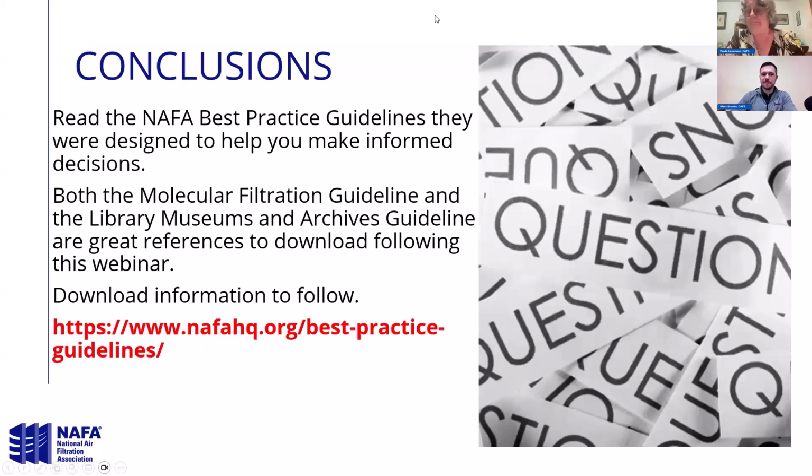Just be careful. I would not contact an engineering firm, no offense, but they have not come up on this yet. And that's to the detriment of those of us in the industry. We didn't teach them well enough. That's not a knock on them. It's on us who didn't educate them. I've seen specs that call for carbon that has a 25 CTC, and in my book, that's spent.